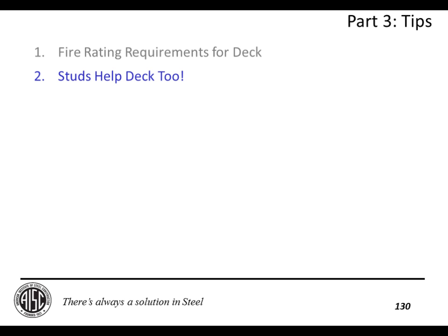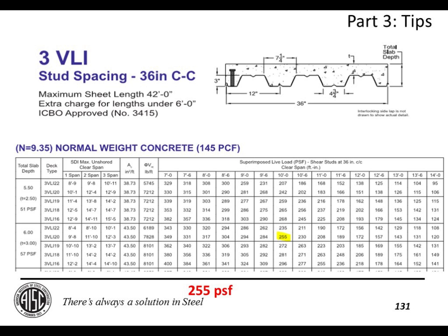So what we're trying to do is prevent the concrete from slipping along the deck. And one way to help out with that is to weld a stud through the deck so that it traps the deck and the concrete together at the end of that deck span. Several manufacturers have put out alternate criteria that takes advantage of this fact.